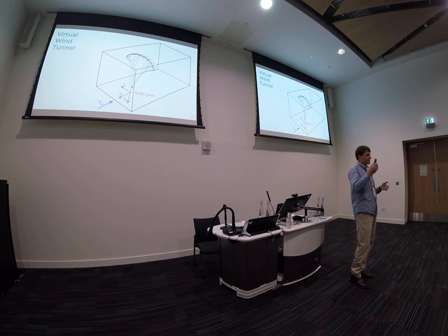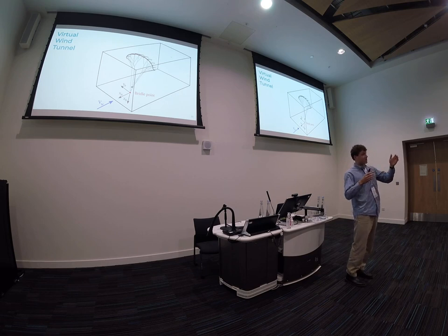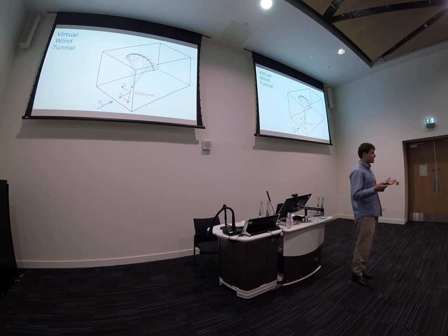And to simulate that sort of moving of the reference frame, one needs to impose the inertial force field that the kite experiences during the turning motion upon this reference frame. And what then would happen, if you do it correctly, is that the kite will try to start moving to the side, but there's an inertial force holding it back, and the kite will remain in place. So hopefully, next time I will see all of you, maybe at AWEC next year, and show you the results of the asymmetrically deforming kite, which remains in place.